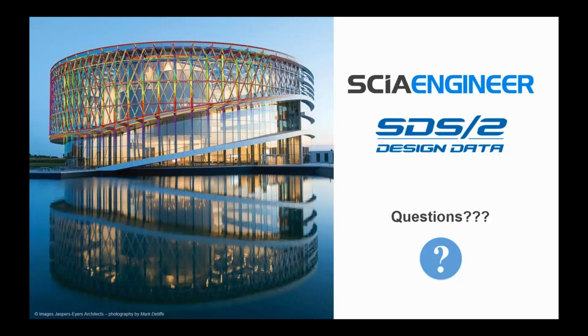Someone had asked some questions about different loading conditions, particularly in SCIA Engineer, asked about different kinds of uplift loading. I know there are other software packages that don't support uplift loading. So SCIA does support uplift. If you're using SCIA's three-dimensional wind load generator, it will also automatically create uplift loads for that.